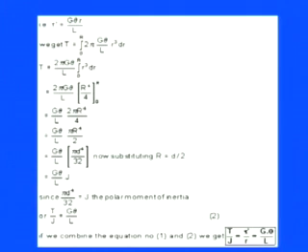So now you see this relation is well set up. In the previous equation we had tau dash by r, or even tau by capital R, equal to G theta by L, and here we have T by J equal to G theta by L. So G theta by L is equal to tau by capital R, or tau dash by small r, meaning whatever the shear stresses are at a particular radius r, which equals T by J.